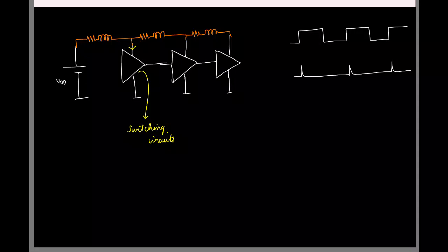So that current has to come here. Now this voltage is proper VDD, but the supply that reaches here, let's say it's VDD1, is obviously not the same as the VDD we want. It is VDD minus the drop across this entire branch.